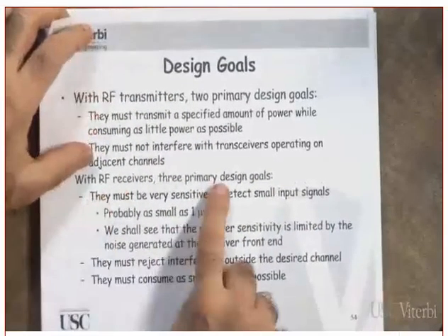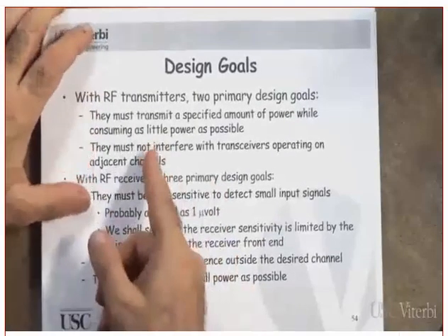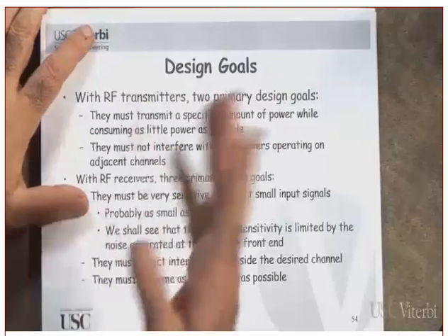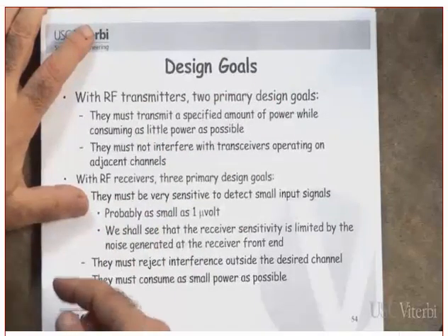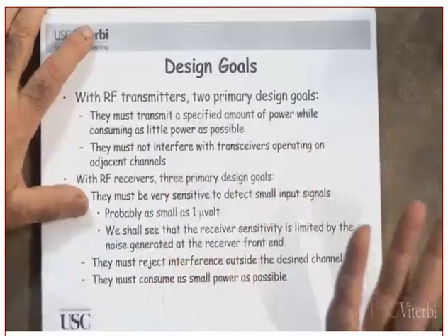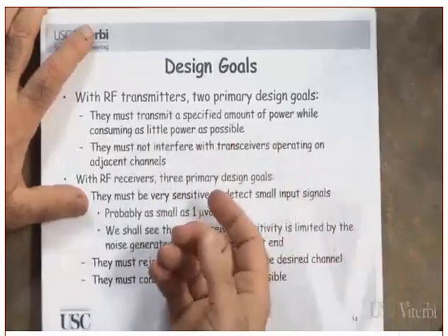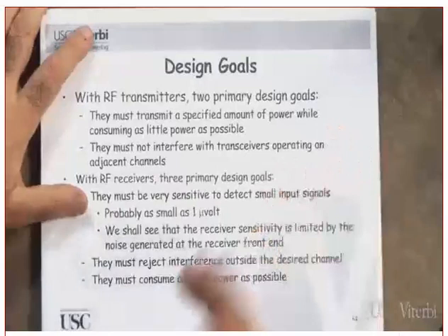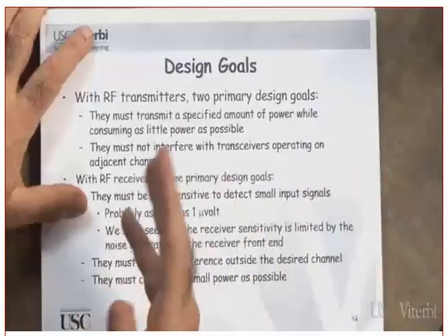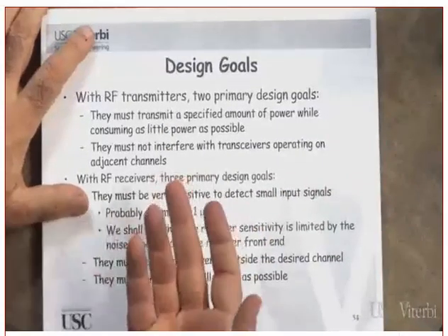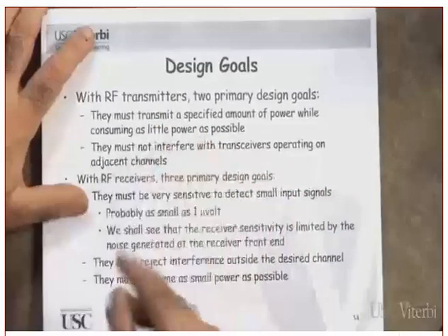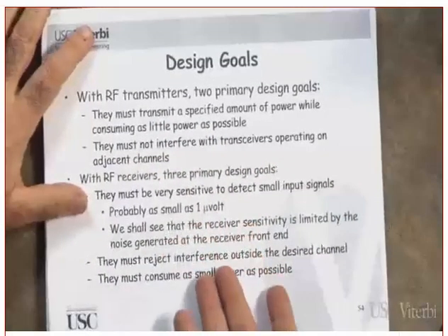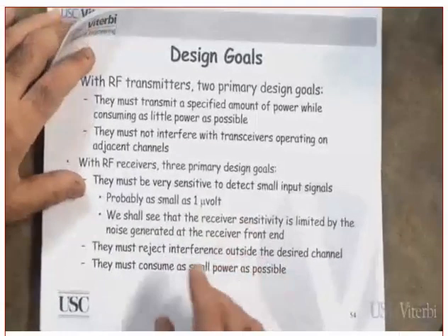Okay. As the receiver, we deal with several issues. By the way, you notice what we did not deal with at the transmitter? I don't worry about interference. I don't worry a lot about noise. Clear? Now, would there be noise at the transmitter? We will see that one of the noise sources at the transmitter will be generated by the local oscillator at the transmitter. We will call it phase noise. Clear? But in general, these problems result from the receiver side. At the receiver side, I worry about it.